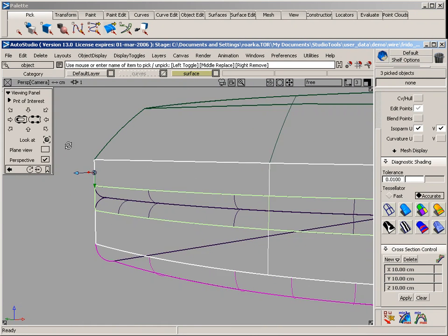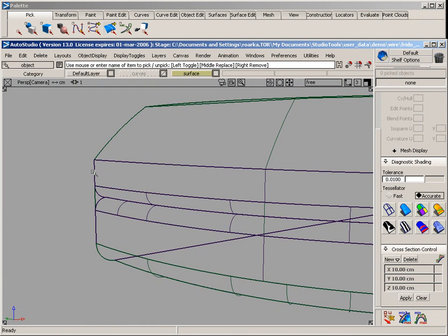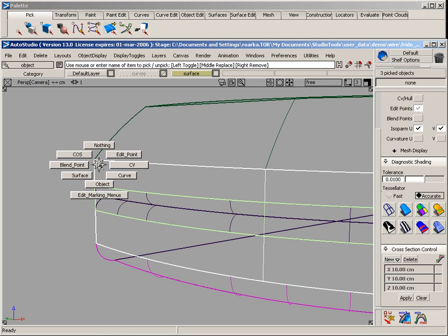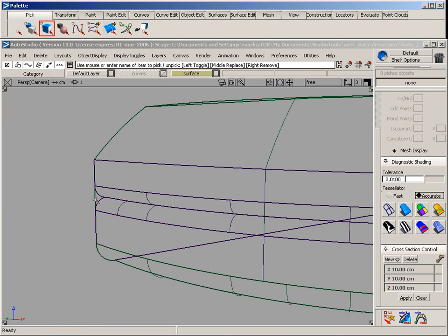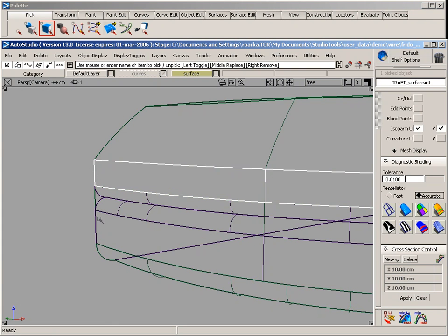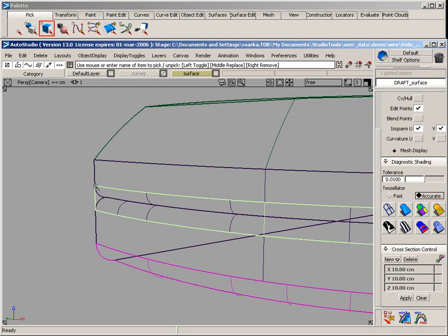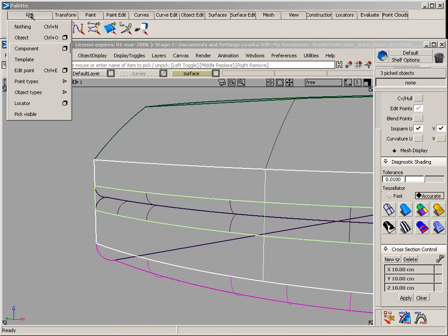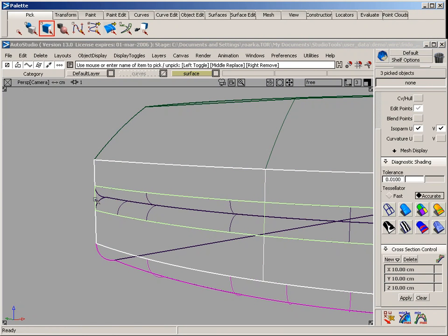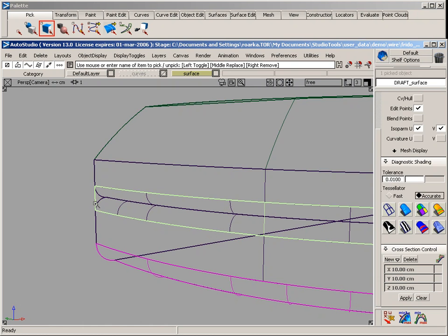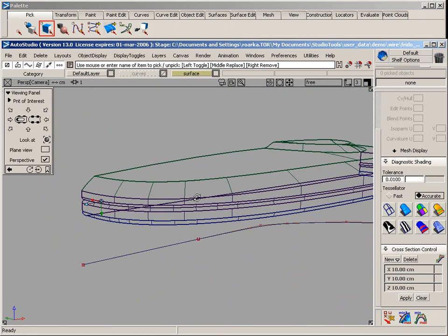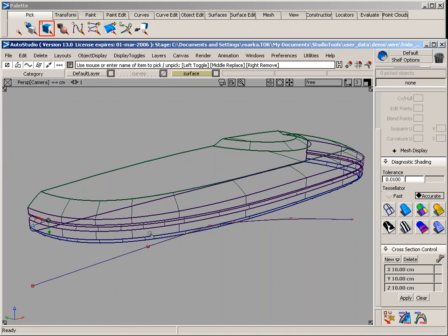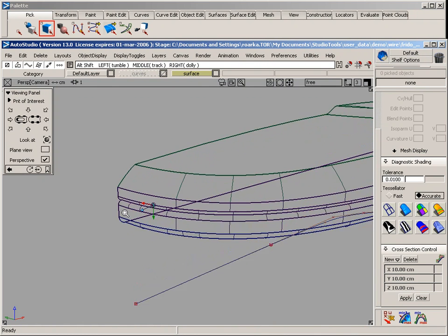let's try this again. This draft surface is actually made up of 3 ones that are grouped together. So when I selected this just a moment ago, notice that it selected it as 1. So I want to make sure I use Pick Component to select only this middle segment and delete it. So this is how I get a quick indication of a part line on here, down the draft surface.